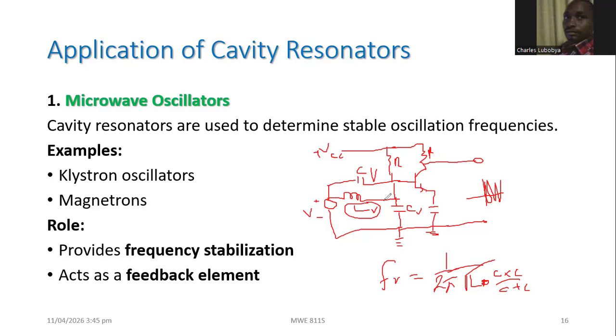And once the oscillation is done, then you need this transistor here to provide a feedback in order to make the oscillations continuous. Without that transistor and the feedback loop here, you would create an oscillation, but then it would die out. So to avoid it dying out, you need that transistor there.